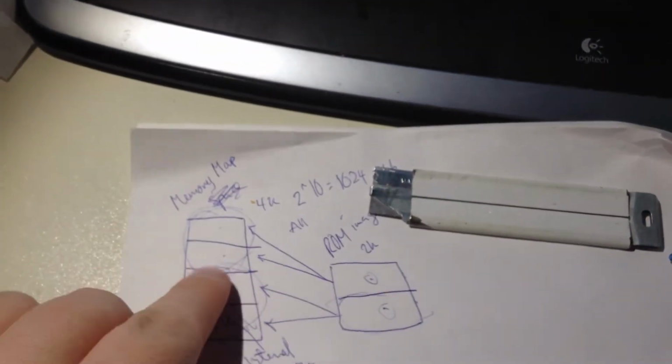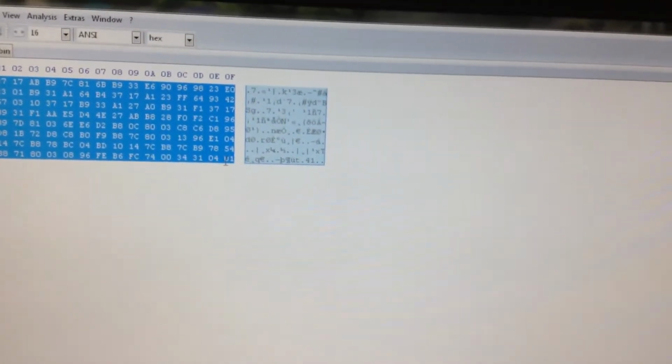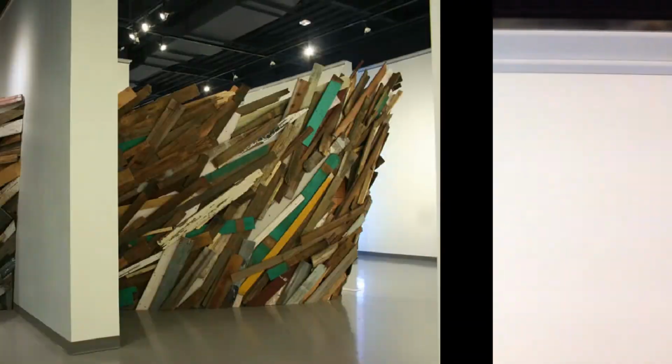And now let's continue copying from 400. So let's mirror that also in the upper part, right? Now I'm taking this one and putting it here and here. That's what I'm doing because my memory chip is one-to-one with the bus. So the memory map of the computer will be the same as the RAM. So copy twice there, save it, Control S, wait a little bit,